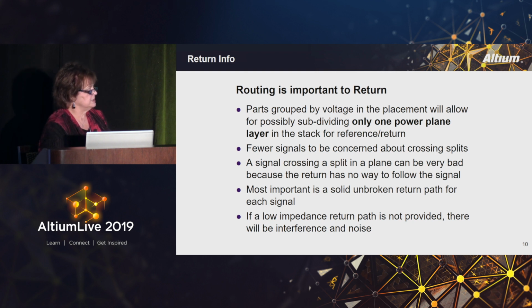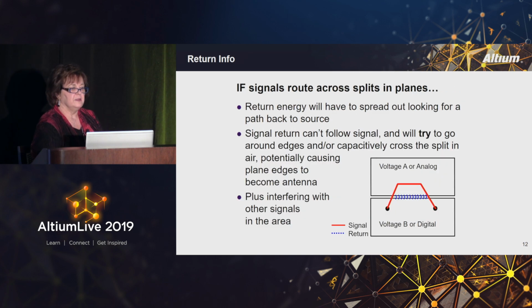And so if you have a solid unbroken plane, then you have a low impedance return path, and you don't have to worry about the energy spreading out onto the neighboring signals. If signals route across splits and planes, the energy can't follow each other, and so it will have to spread out looking for a path.